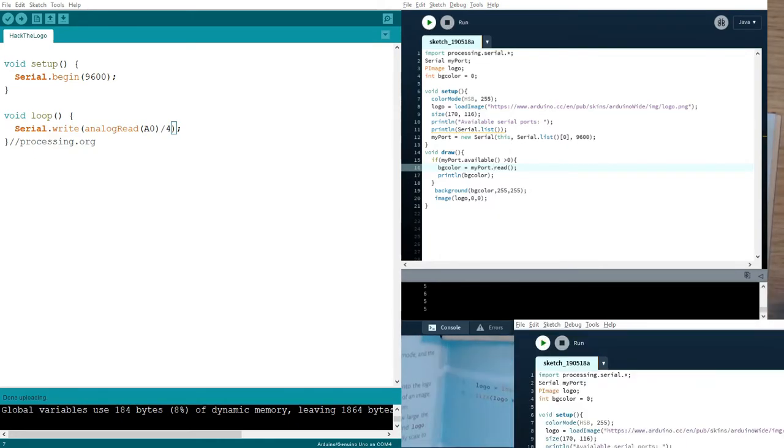Play it again. Okay, wait, it's getting something. It's 5. It's still 5 and 6. It's just 5 and 6. No, this is not right. This is not how it should be working. Arduino clearly says that it should be reading from analog pin A0, then dividing that by 4, which should give us a number from 0 to 255. When I was printing it out, we saw this. But now it's just going either 0 or 5 and 6.